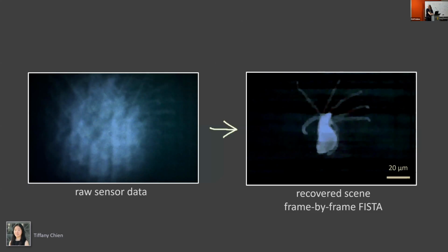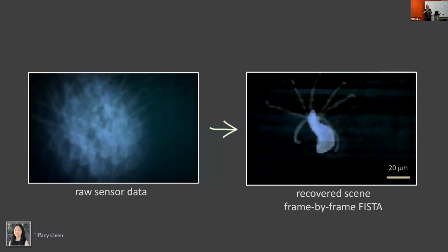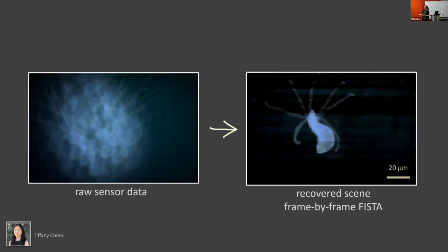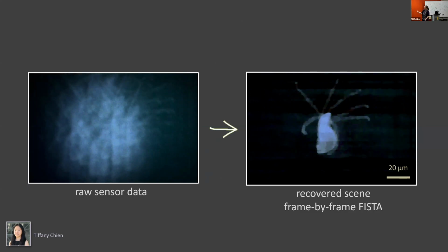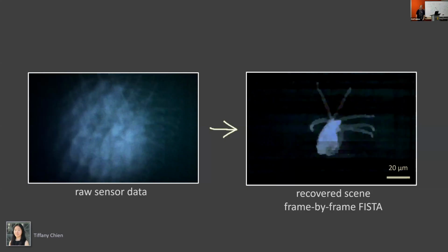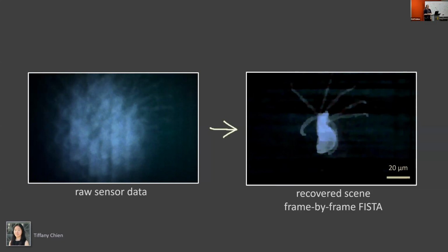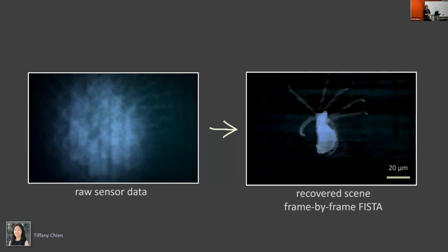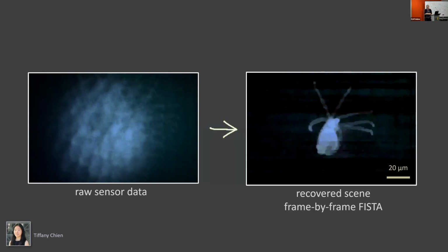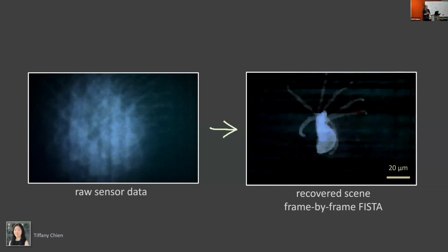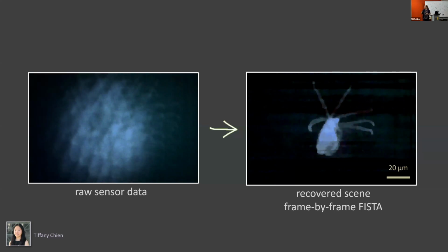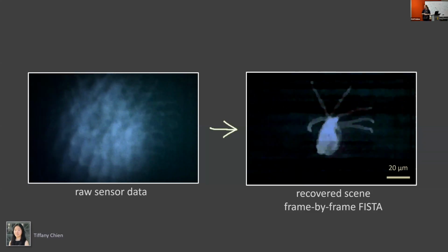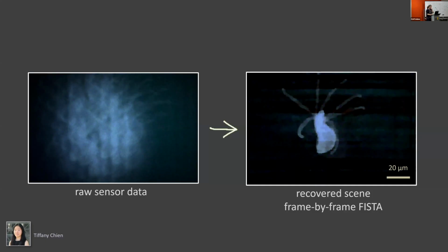Another approach we went to trying to solve these artifacts. We did a lot of these in different orders in time, so it's trying to tell the story to make sense, but this was back when we still had lower quality to start with. Tiffany was working on space-time methods, which we do a lot of right now, trying to use video data to reconstruct better images. This works better if you're doing multi-shot computational imaging, but this is single-shot computational imaging, but we can still take advantage of space-time redundancies or low-rank behavior in space-time if we have a video from this DiffuserCam.